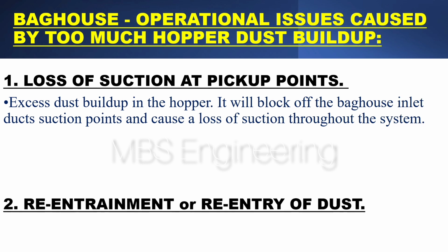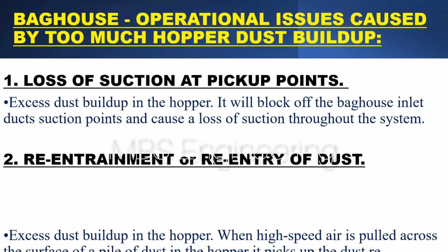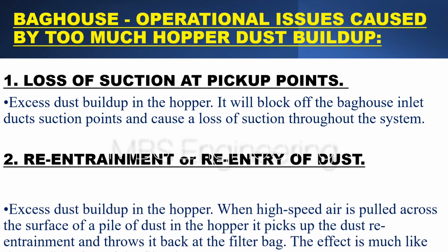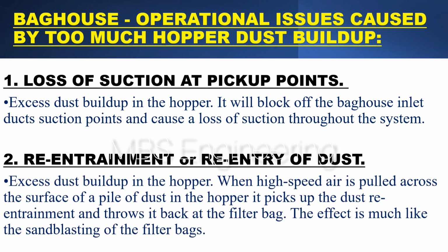Next, the second issue is re-entrainment or re-entry of dust. Excess dust buildup in the hopper. When high-speed air is pulled across the surface of a pile of dust in the hopper, it picks up the dust and throws it back at the filter bag. The effect is much like the sandblasting of the filter bags.